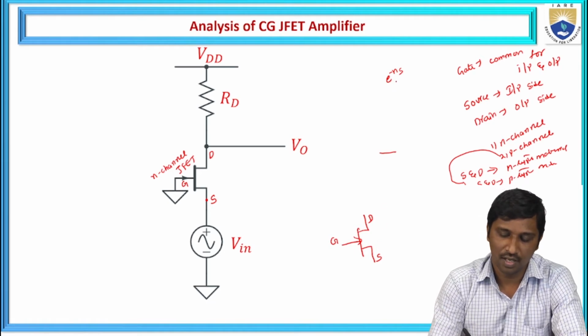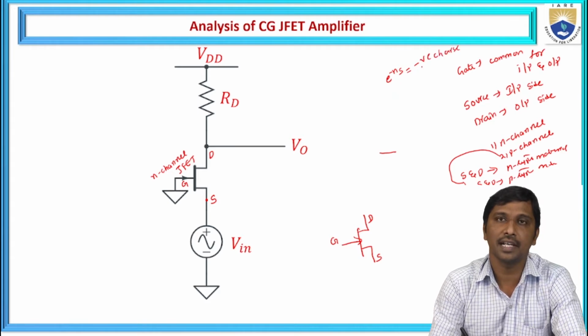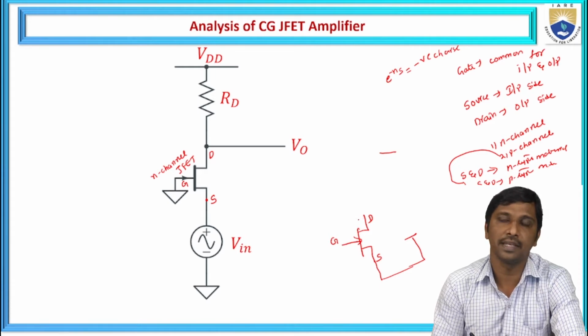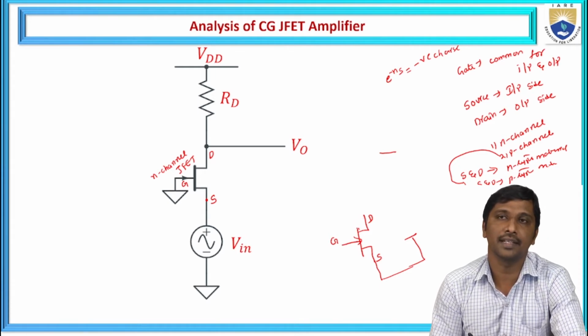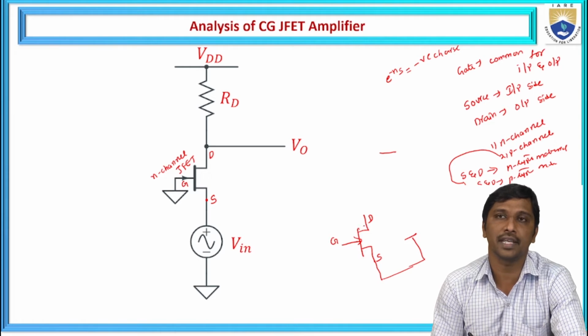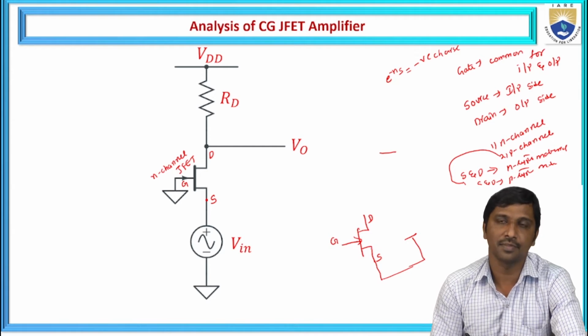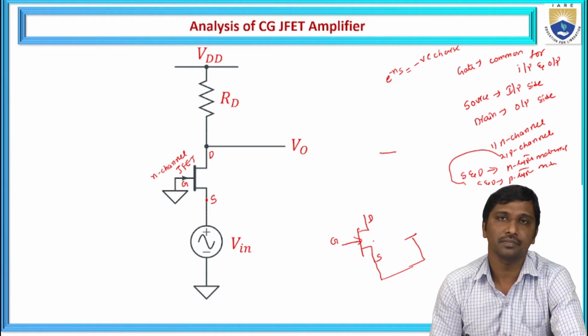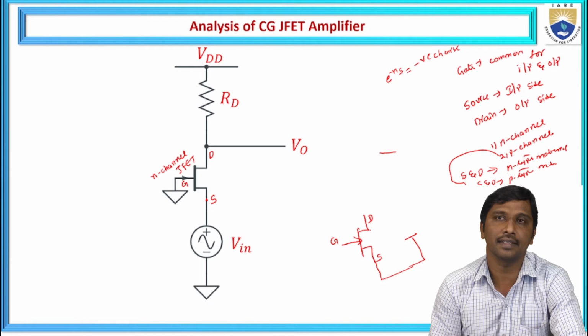We know that the electron is a negative charge particle. If we apply the same kind of charge to this negative particle, it repels the electron. That is the reason the source is biased with the negative pole of the battery. To allow conduction, we need to diffuse the charge carriers from the source to the drain, and all the charge carriers that are repelled should be attracted by the drain.